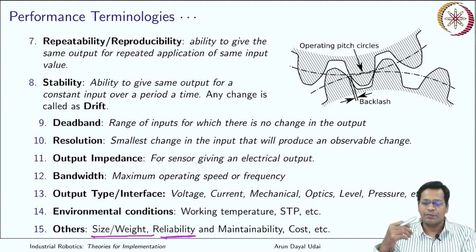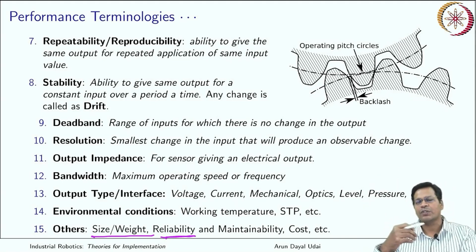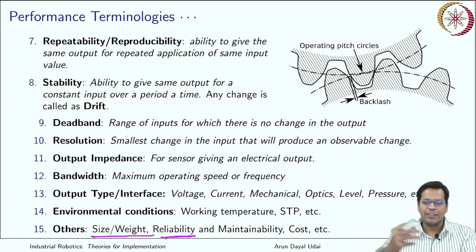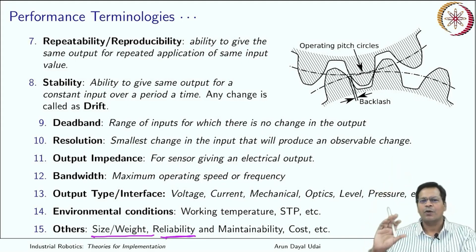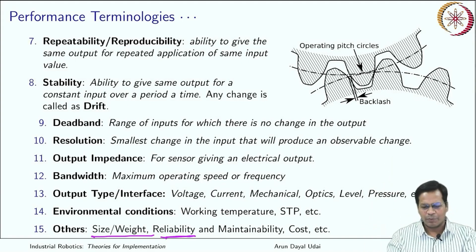But if that force sensor is able to take up that load at least for a second, you are fine and your device will not go bad. Those are very expensive sensors. So at least for a small period of time you can overshoot, but the normal range is 100 Newton. So you got my point. That is the reliability of such a thing.